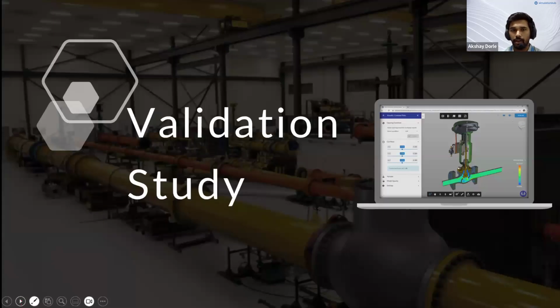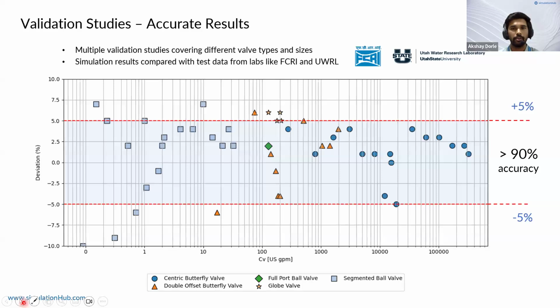So we have seen the case studies, we have seen how AVC works. A genuine question to ask is, how can we get the trust on these values? We have done extensive validation studies, so we'll have a look at it. This plot shows the accuracy of CV prediction using AVC as compared to the physical flow loop tests, which were conducted in FCRI and in Utah Water Research Lab.